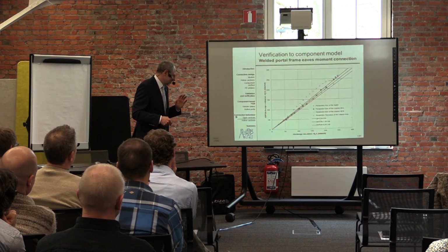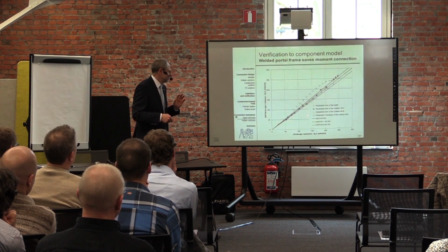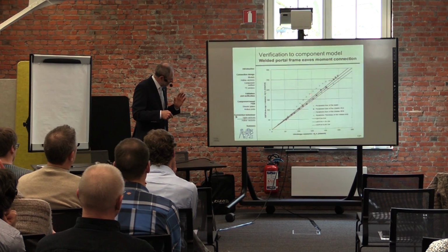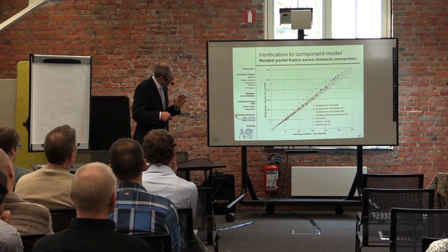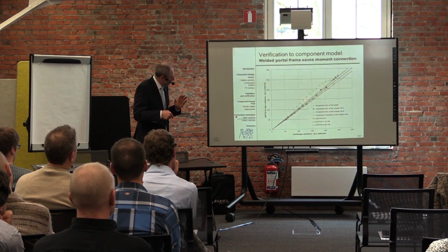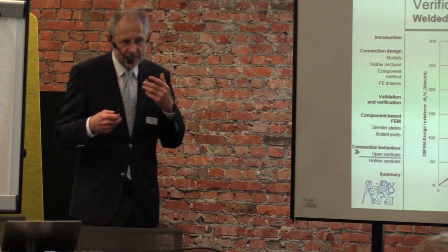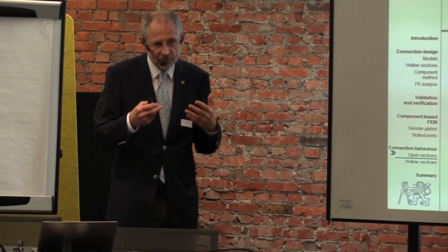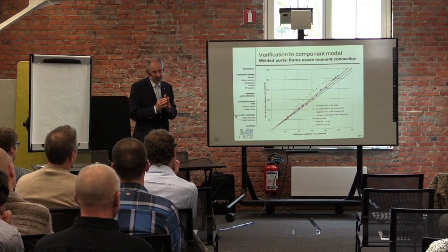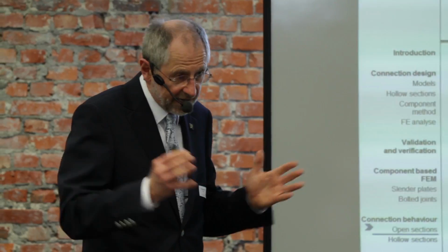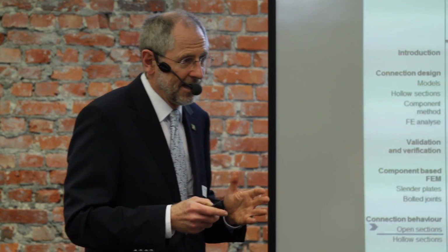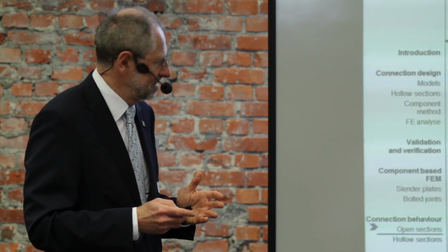The Eurocode procedure is not taking care of it. It's a bit simplifying. It's not too far, but if we go for a more advanced model, we get a bit less resistance compared to what you have in Eurocode because of slender webs. Simply, it's not taking care of slender webs, and we are taking care of slender webs.